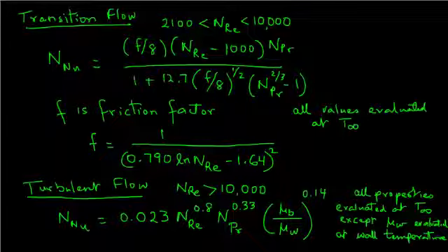These expressions are useful for finding out convective heat transfer in case of air or for water. We just have to find the right properties and substitute those numbers in these equations. Those properties are obtained from tables which are given in the appendix of the textbook.